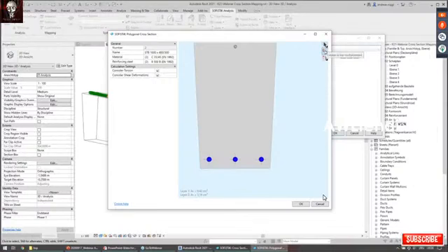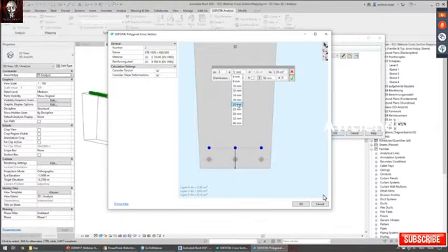I will now add another layer of reinforcement, another bottom layer of reinforcement with a distance of 50 millimeters to the first layer, and configure it again. So 3 bars again of size 20 millimeters. And assign it to layer number 1. So there are layer numbers assigned, which you can then control later in the design process, for example. So each reinforcement layer has a number in SOFiSTiK.